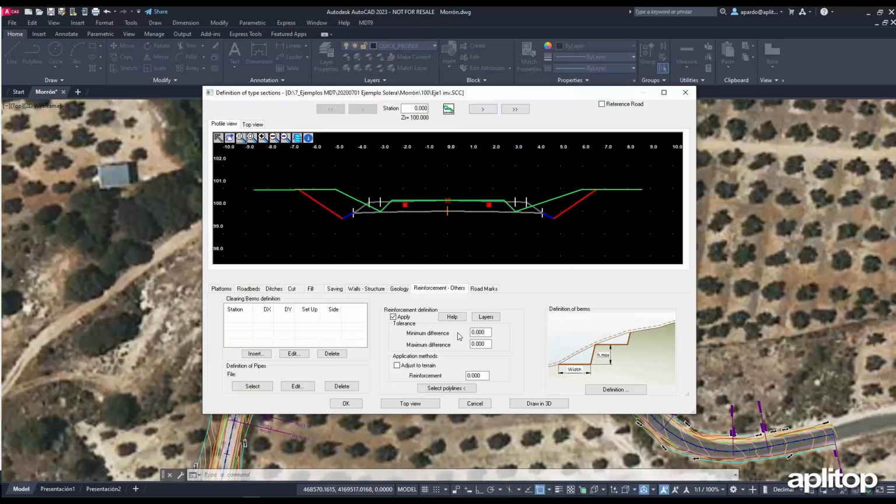This value must be greater than the difference between the elevations in the natural terrain and the subbase at the edge of the reinforcement. The value depends on the geology of the natural terrain. Normally, similar values are applied to the roadbed or higher to include cut area where the new vertical alignment is lower than the existing terrain and it is possible to keep the last layers of the old pavement.